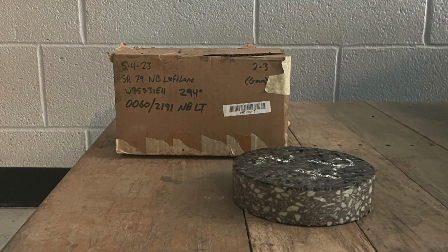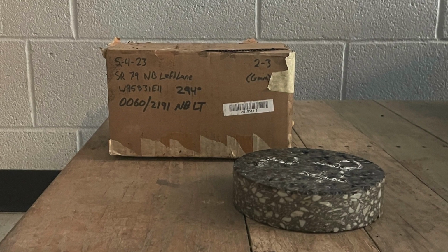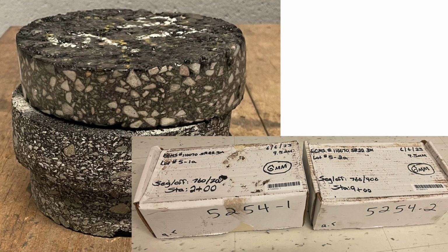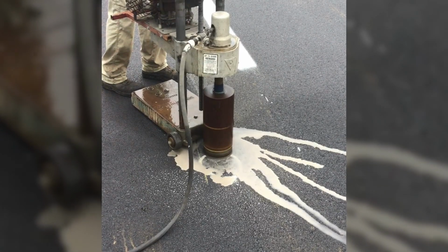A sublot will only be considered complete if there is both a loose box and a core sample. For example, if 3 cores and 2 loose box samples are lifted in the final lot, there would only be 2 complete sublots, and the 3rd core sample would be discarded because it does not have a companion loose box with it. Let's go over a quick example to help tie everything together.